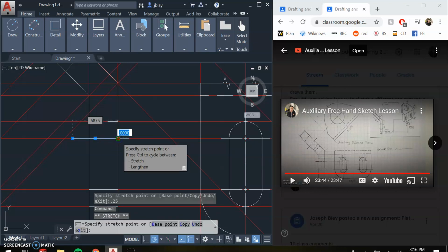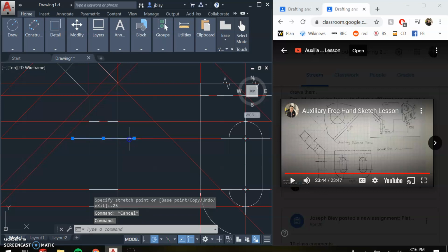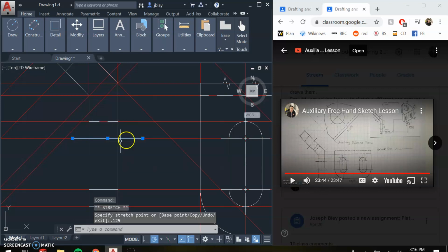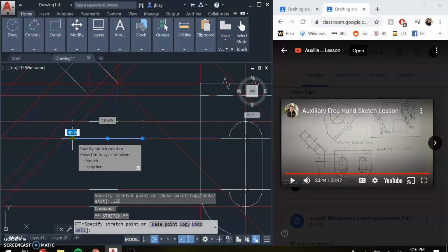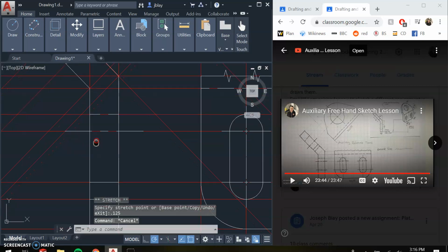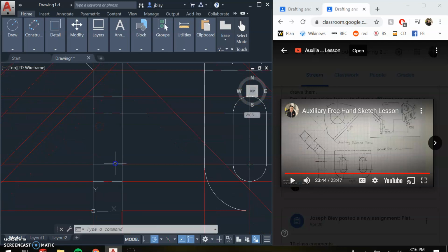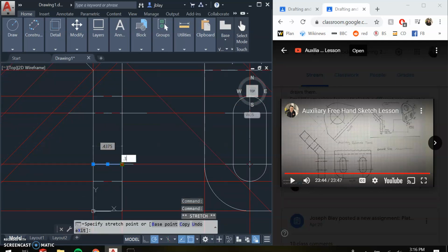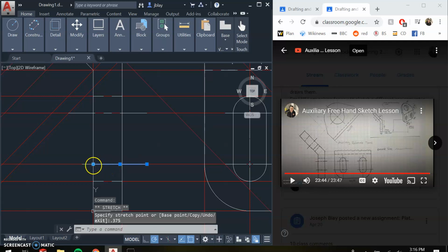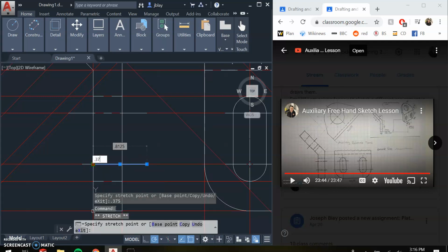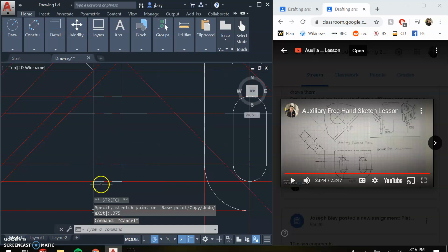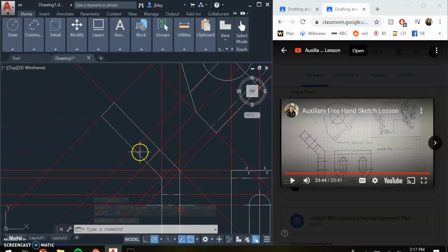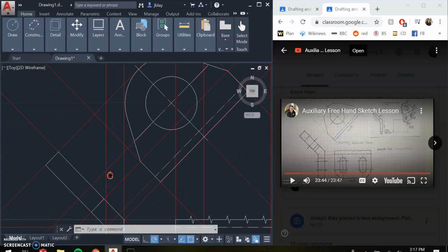That makes them visible. Nope, we're going to extend a little bit further to make that break visible. So another 0.125 inches in each direction, so a total of 0.375. Okay, good. So now when I select these, I'm going to extend by 0.375. Okay. Now I have my center lines for this slot, and I have to do this one down here.